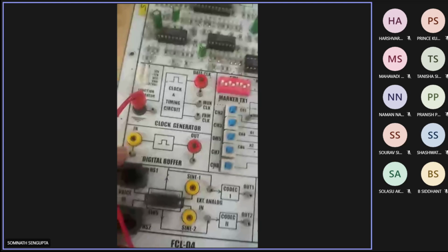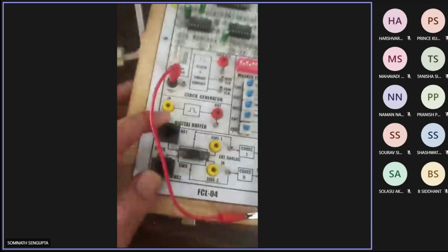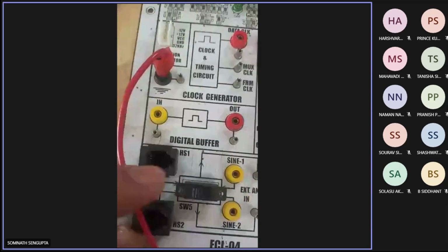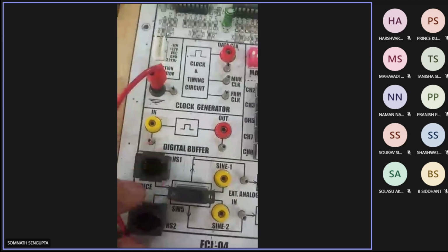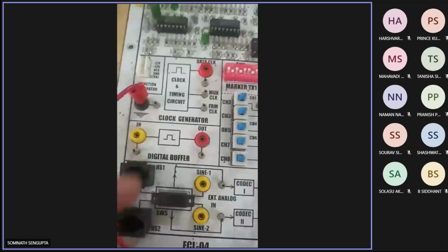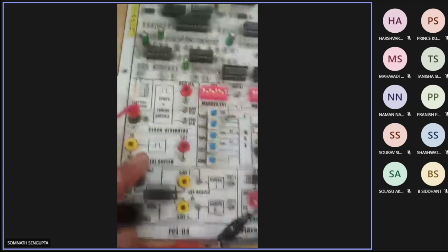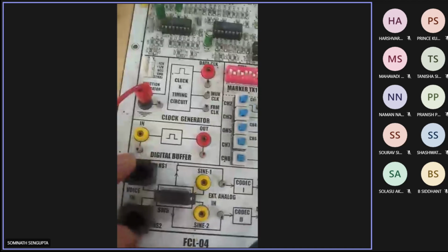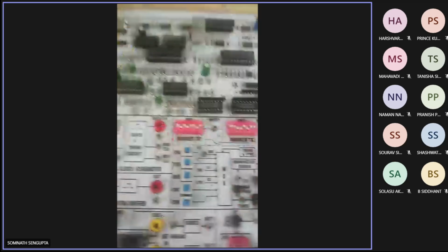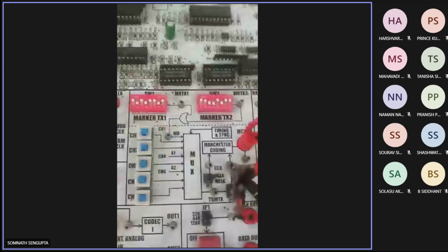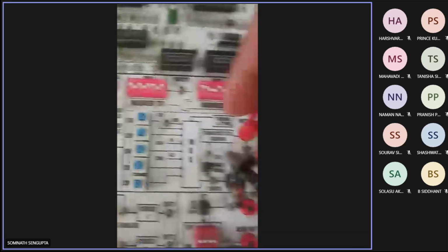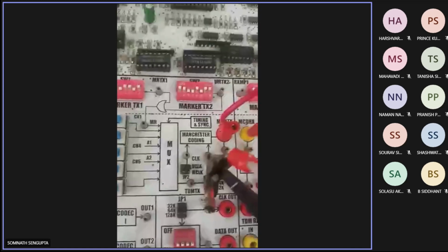You can use the receiver; we are not connected to the receiver port here. You can use 2 landline receiver sets, handset 1 and handset 2. So voice from 2 users can be transmitted using these 2. Then they are multiplexed, and a certain coding scheme, Manchester coding, is applied here.